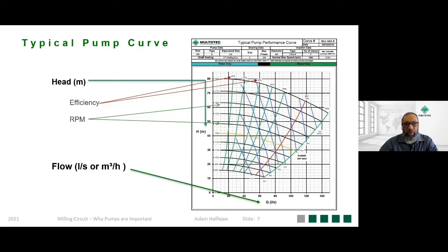Normally, with water pumps you'll have a single speed and you trim the impeller, but here it's very different because it's difficult to make different trims of impeller with the material being hard, and therefore we vary the speed rather than the diameter of the impeller. And one other very important factor generally in slurry pumping is your NPSH.